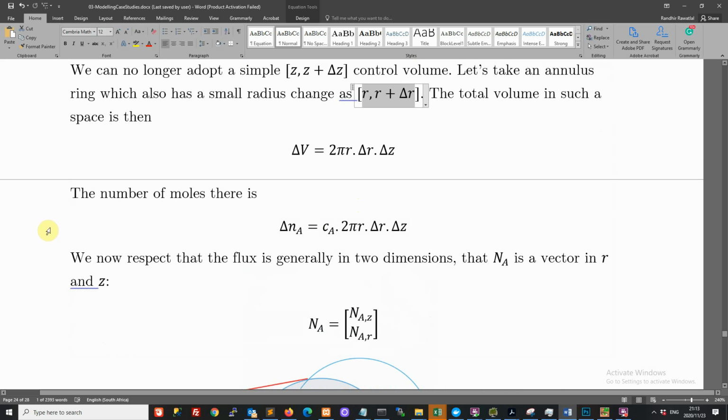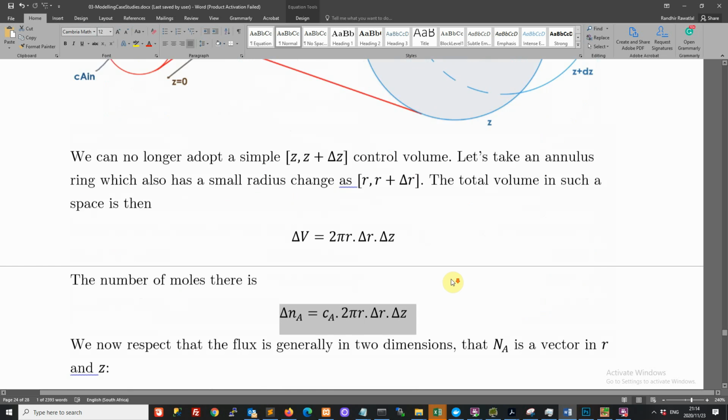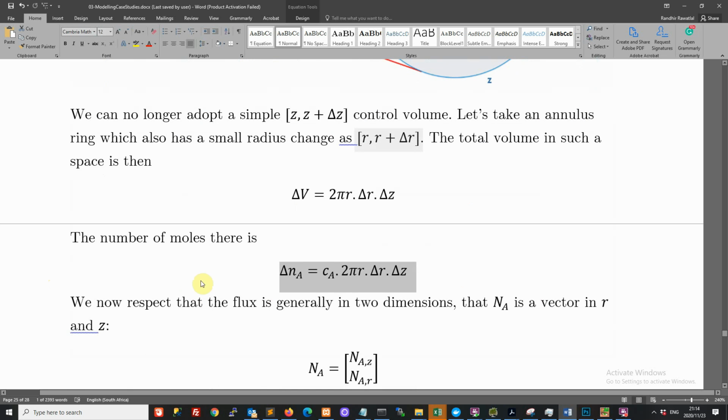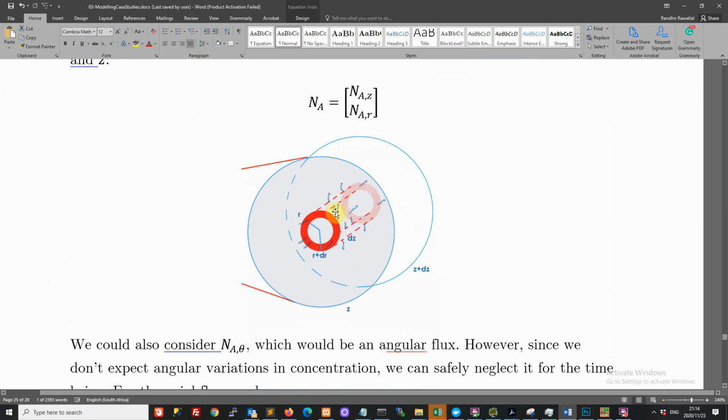Then also spend some time trying to capture the number of moles in that space. So if we have concluded this is the right type of subvolume, then estimate the number of moles in that subvolume, and you should come to that amount. And then, quite importantly, sketch out the fluxes that you have across the space, and then write down the molar fluxes at each surface here.